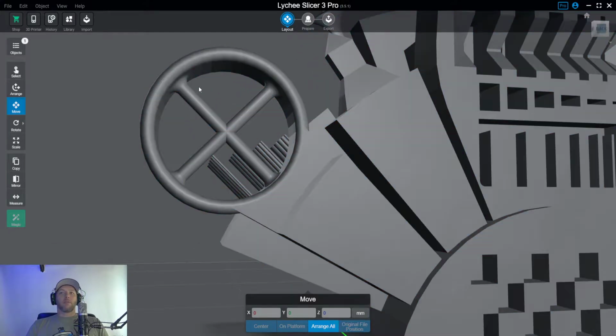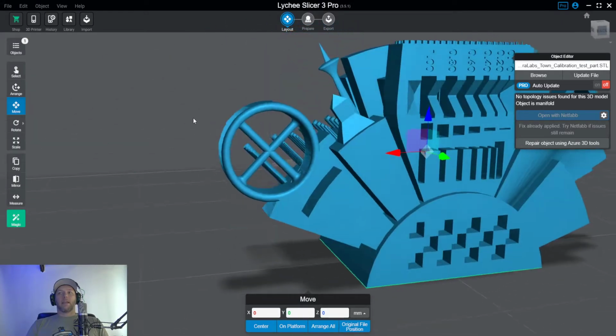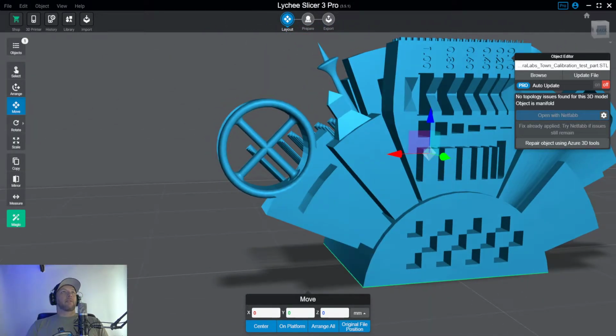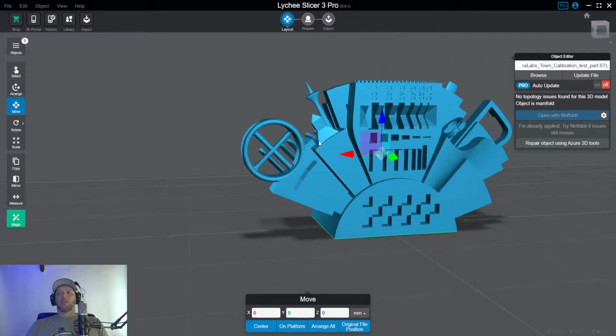I've had times where the cross is all broken out, and those times are usually underexposure. So we want to have a quick look and get an idea whether or not that cross is actually in there. Those are pretty much the 3 points I hit when I'm looking to tune my printer.